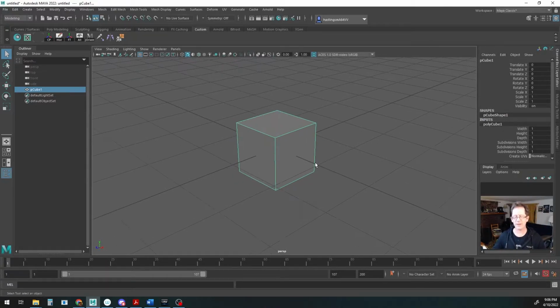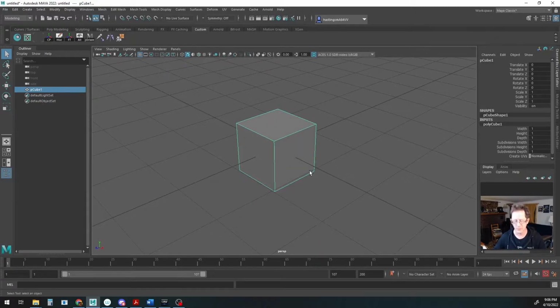All right, so now we can also move this object in the world, and we modify it by using Q, W, E, and R. You can see over here when I do that, that these are changing. This is select, which is Q. This is move. This is rotate. This is scale. So get used to the key commands.